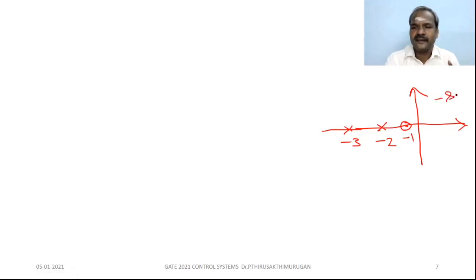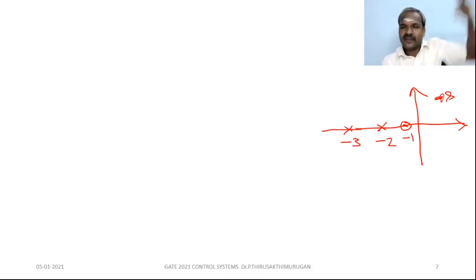This is the S plane. The root locus branch always starts at poles and ends at zeros. There are 2 branches. One pole can terminate at the zero. What about the other pole? The other pole terminates at infinity, at K equal to infinity, somewhere far away.